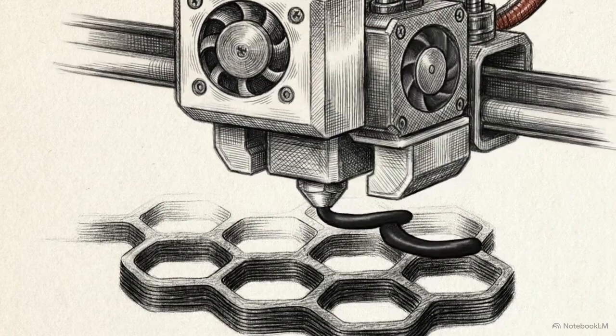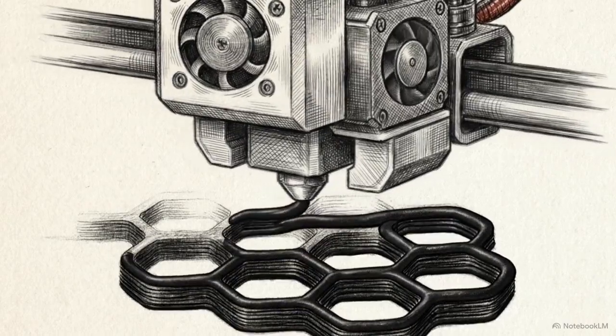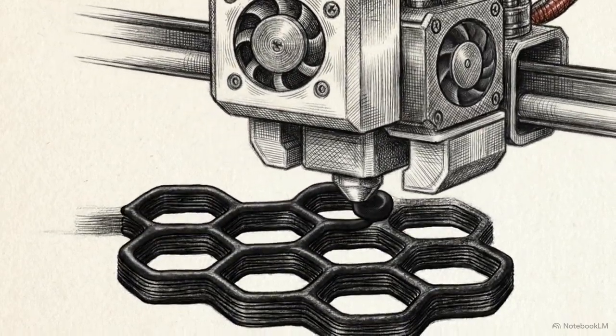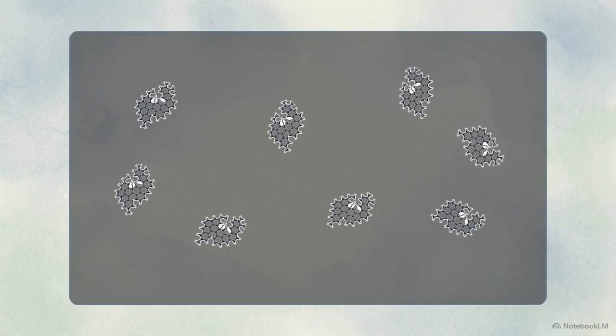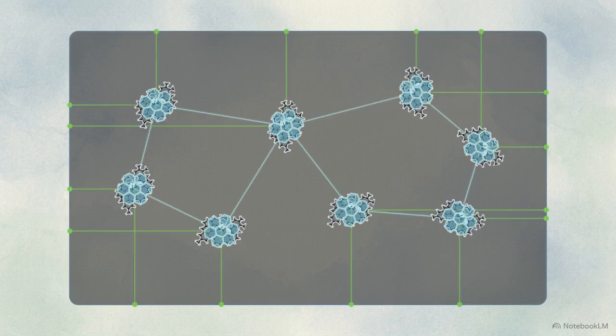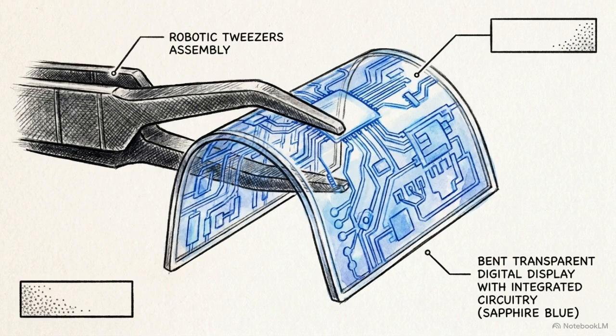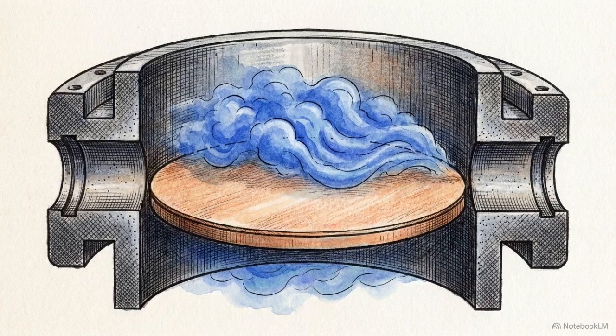For example, advanced composites, epoxy resins, and 3D printing filaments do not require perfect electron mobility to function. They rely entirely on the sigma bonds. Dispersing highly scalable, chemically defective RGO flakes into a polymer matrix leverages the raw tensile strength of the lattice, reinforcing the host structure. High-frequency transistors and flexible optoelectronics have a strict zero-defect requirement. To function, these devices require the uninterrupted charge carrier mobility provided by the continuous pi band. Therefore, they rely exclusively on high-quality CVD manufacturing.